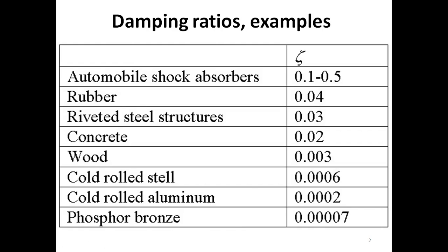There is damping. But if the damping is small, then in that case we could ignore the damping for the sake of simplicity of the modeling. What would be the advantage? The advantage would be a simple equation of motion, a simple derivation, and a simple analysis. But the disadvantage would be error in your computation.